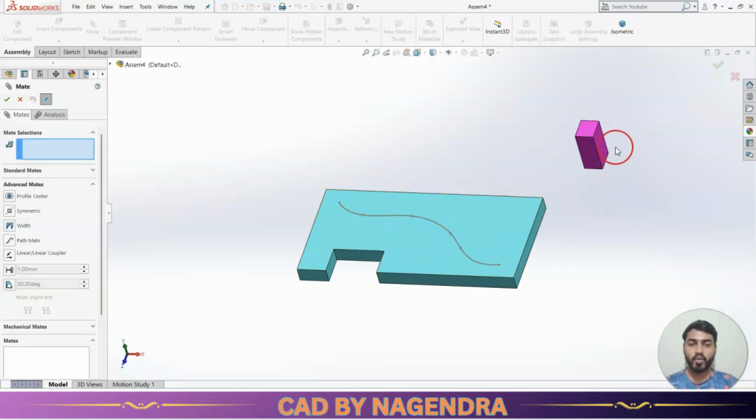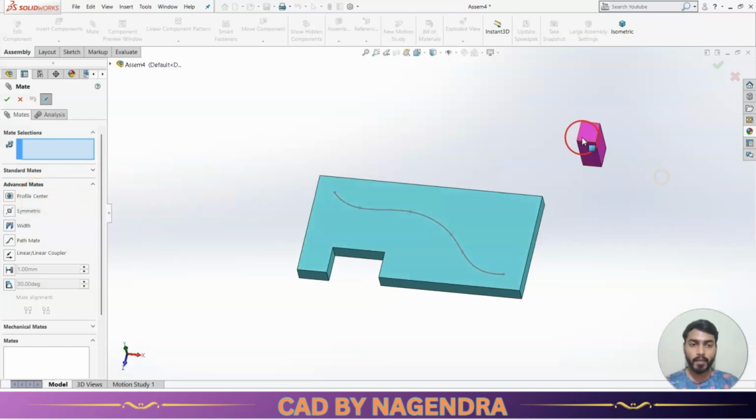Then only this block will settle exactly at the center. So with standard mates we apply 3 mates here. But in a simple way, by using profile center, with a single mate we can make this block exactly at the center. Let me show you that.